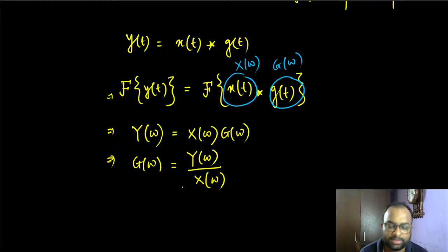The three Dirichlet conditions must be satisfied. The signal must be bounded. First of all, the signal must have a finite number of extrema and a finite number of discontinuities. So these sort of things. Now many standard functions do not satisfy these sorts of conditions. So Fourier transforms were not applicable to those sorts of functions, right?